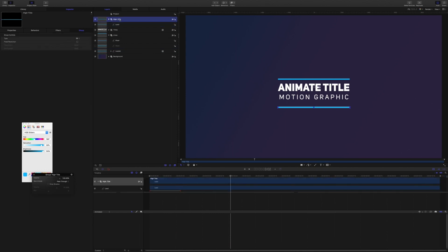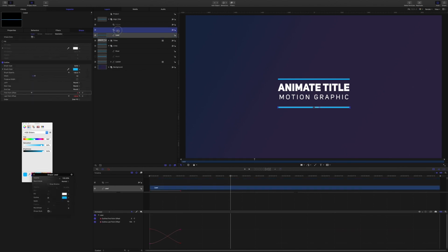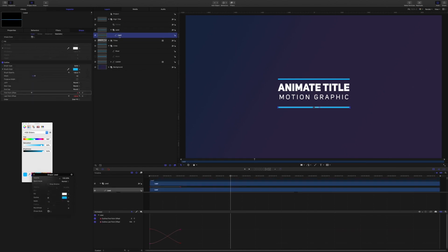Now I'm going to add two more groups to this high title group. I'm going to name the first group lead, the second group follow, and drag them both in there. And I'll drag that lead line into the lead group, and I'm going to reset the first and last point offset.